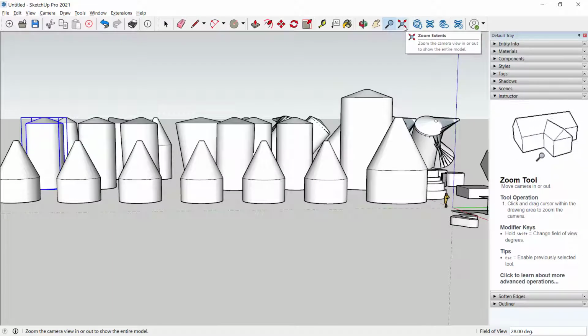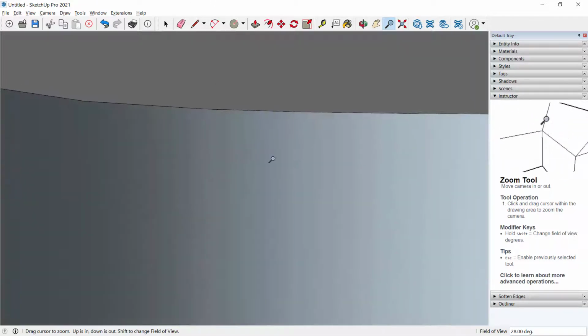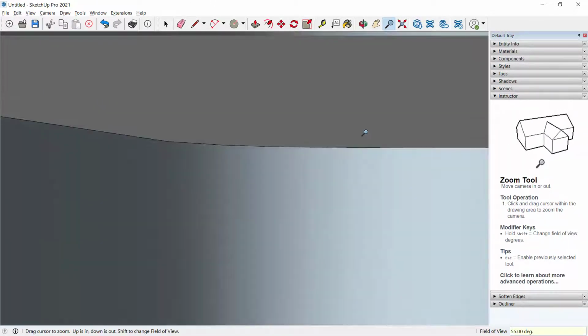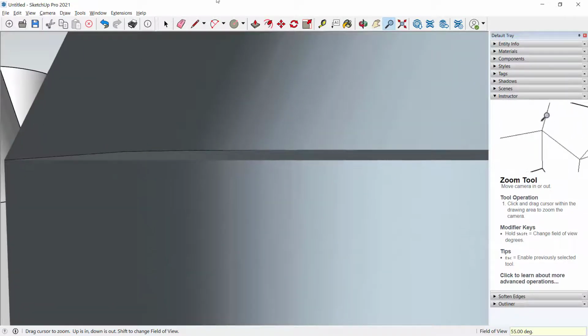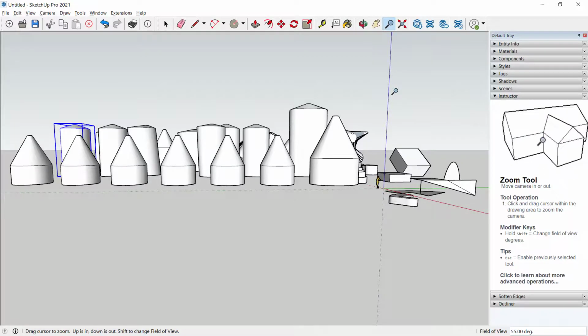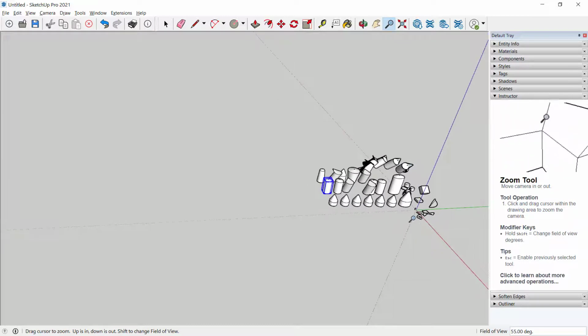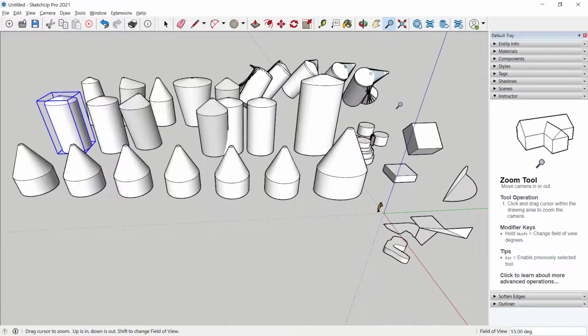And then this Zoom Extents button, very handy for getting you out of trouble, because sometimes you'll get inside an object and you'll be inside looking around and you can't see anything and you don't know where you are and you're trying to say, help, get me out of here. Zoom Extents just zooms out to everything it can find. And sometimes you'll find a chair or a tree about 100 miles out in the distance, and you can't figure out why your model is operating so slowly. Hit that Zoom Extents, and it will find any lost, lonely objects out in outer space.